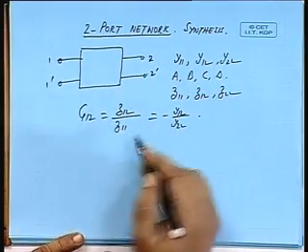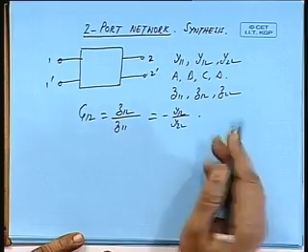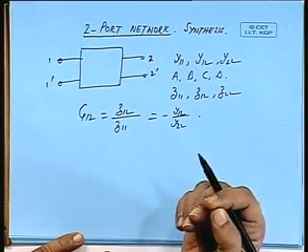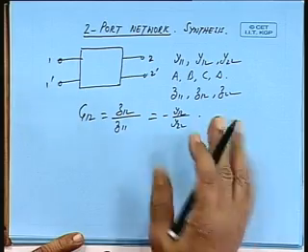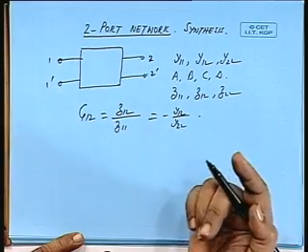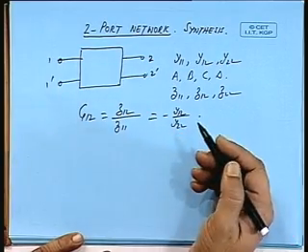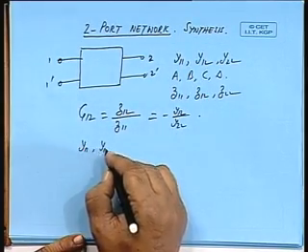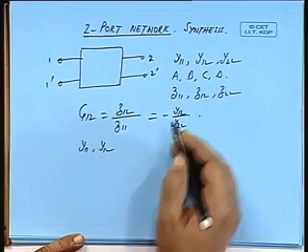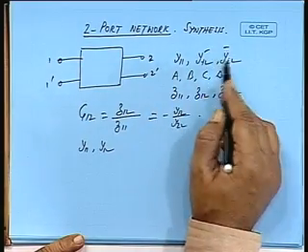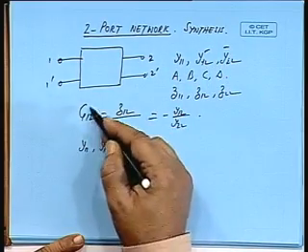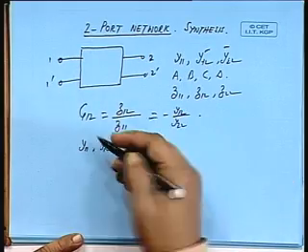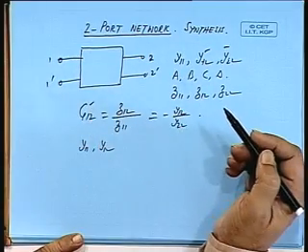Alright. So, the specifications can be many types, unlike a one port network where you are given either ZS or YS. YS is just the inverse of ZS. So, you have one specification. Here the specifications can be in terms of say Y11 and Y12, or Y22 and Y12, any two can be given, or maybe just the gain function. Alright. So, how to realize a network to meet these specifications?